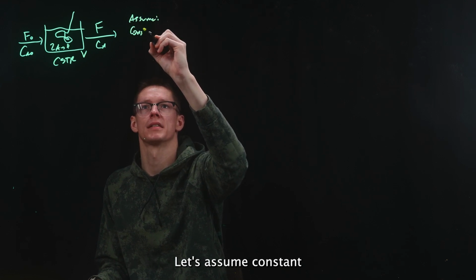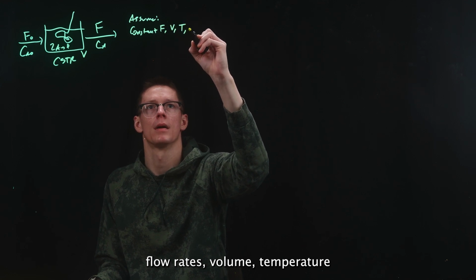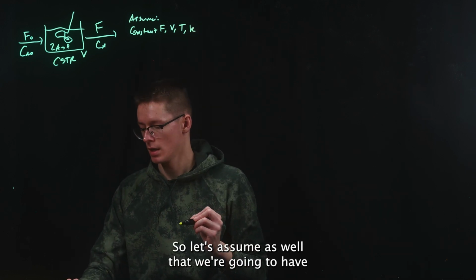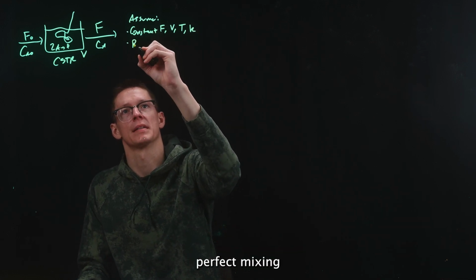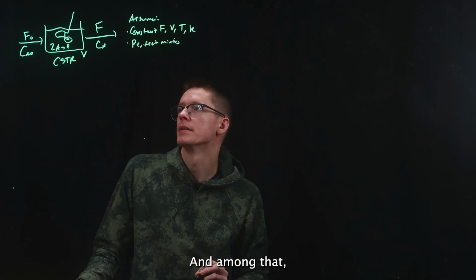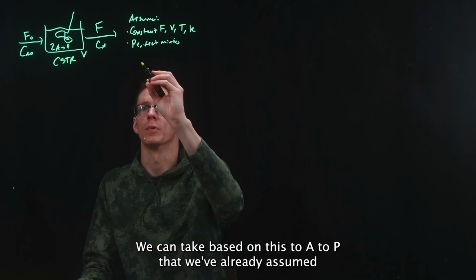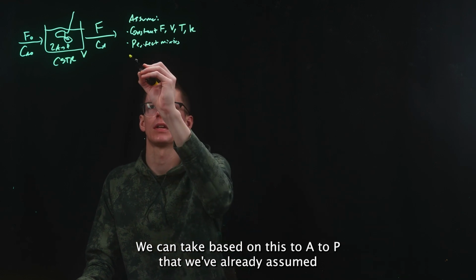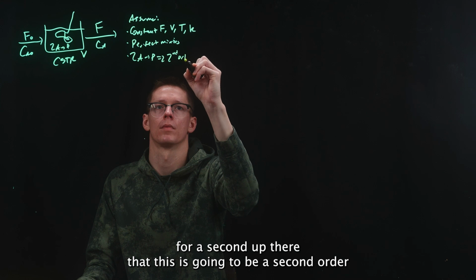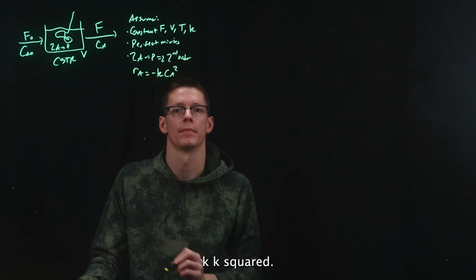Let's assume constant flow rates, volume, temperature, and reaction rate constant k. Let's assume as well that we're going to have perfect mixing in our system. And among that, I think for right now, that should be good for our assumptions. We can take, based on this 2A to P that we've already assumed for a second up there, that this is going to be a second order reaction, meaning the reaction rate is negative k Ca squared.